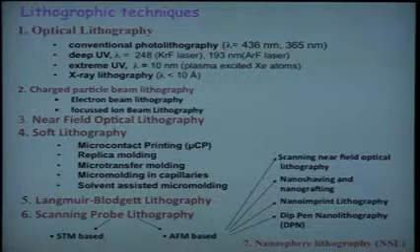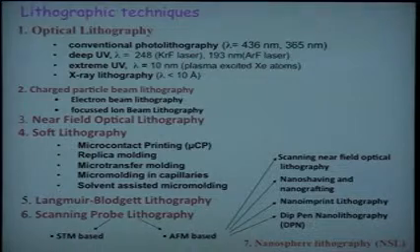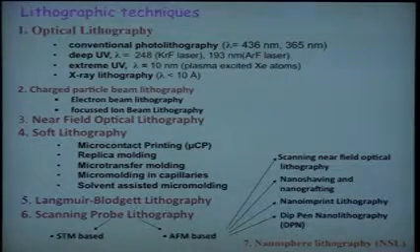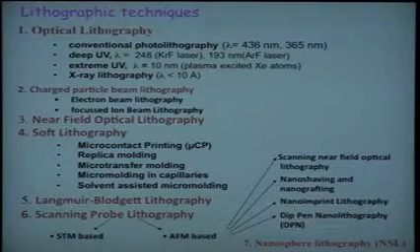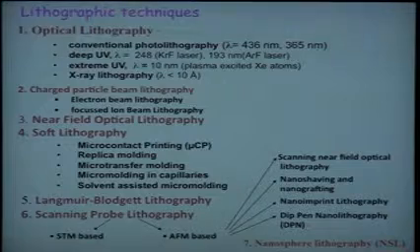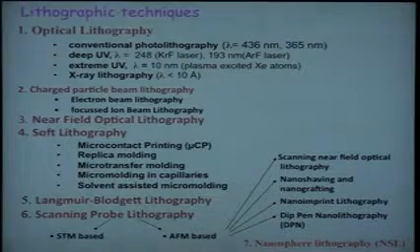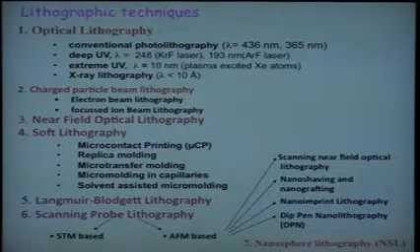When you talk about optical lithography, you have actually a broad beam of light which is shining from the top or from bottom in a given direction, and then you are using it to pass through a given mask. Actually the mask contains the kind of pattern you want. So the light is passing through that, and the kind of resolution you want to reach would seriously depend on the wavelength of this light. I think we'll go through the details in the next slide, but you can see here light of different wavelengths is used, even down to X-ray, just to increase the resolution of the pattern.